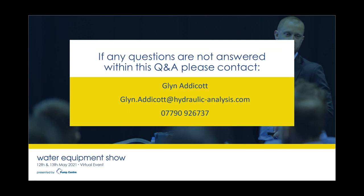I've got another question here for you, Glyn. Again, anonymous. How does the digital twin receive the data? Okay, that's a really good point, and that's the bit that's been interesting for us. In our applications in places like the Middle East and China, it's through a SCADA system. We connect directly to the SCADA system through what we call an OPC client. It's a communication protocol that passes information through the SCADA system to our simulator.